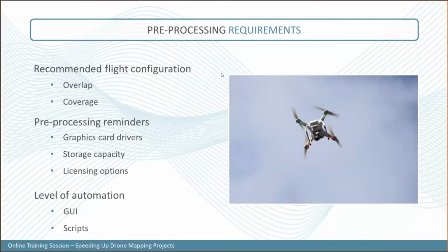Also, in terms of ground sample distance, as much as possible, we want to have something that's constant throughout your project. So if it's possible with your drone during your collection, try as much as possible to use a terrain following option. This way, you'll make sure that the ground sample distance will be as constant as possible during the collection.